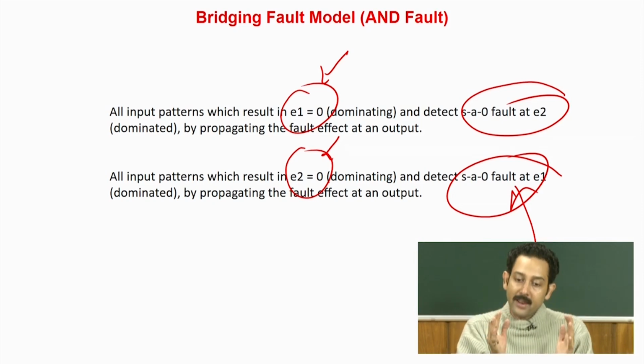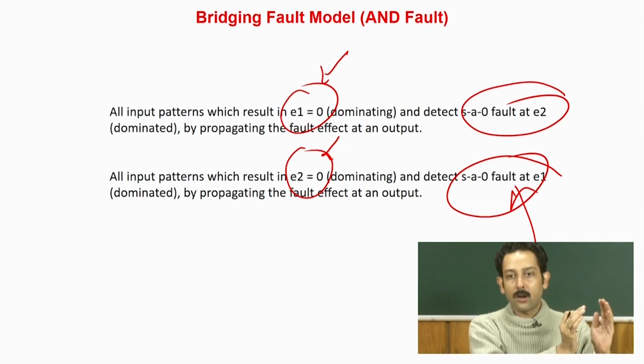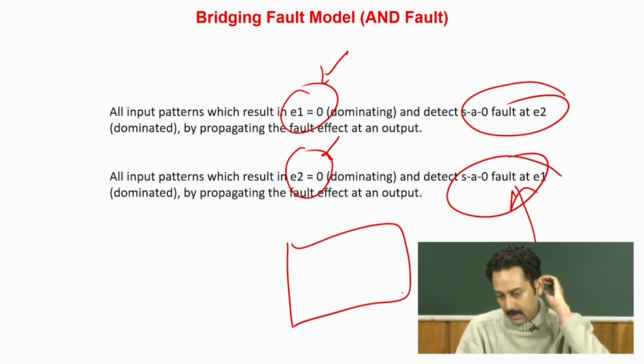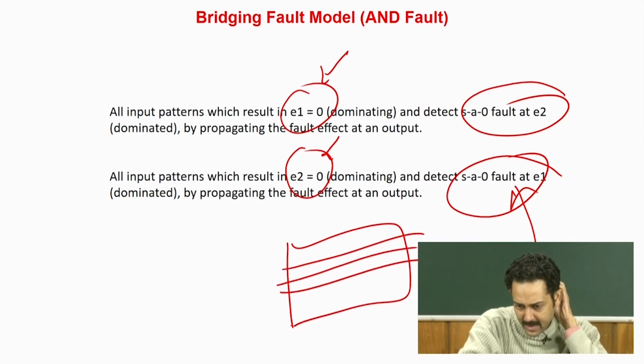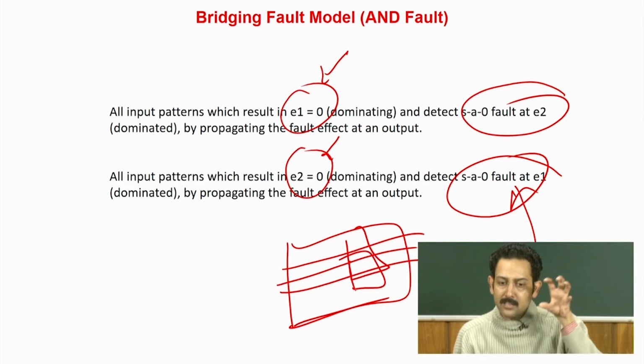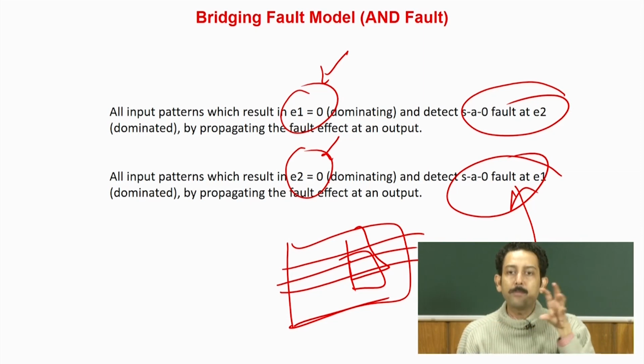So people try to restrict their bridging fault models to a small part of the circuit. Maybe they assume that there is a lot of congestion in the layout over here, and there they will start making a moving window concept. So these advanced fault models generally are restricted to some specialized zones.